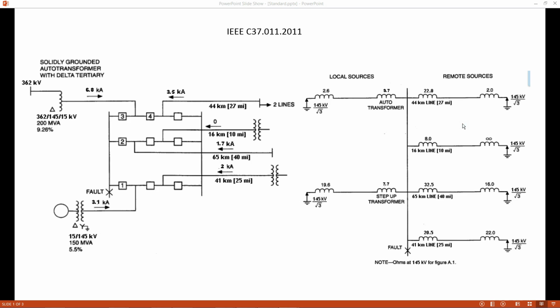So as the first step, we will build this model using the same approximation, so that the parameters are constant, as we can see here. So first we'll use a constant parameter model of line and not frequency dependent. Also, as you can see here, only the inductances are considered. In our case, we will consider also 1% of resistance, because it's to avoid all kinds of numerical problems. It's not a good idea to not consider the resistance when we cut a current. So here we'll put 1% of resistance to be more realistic.